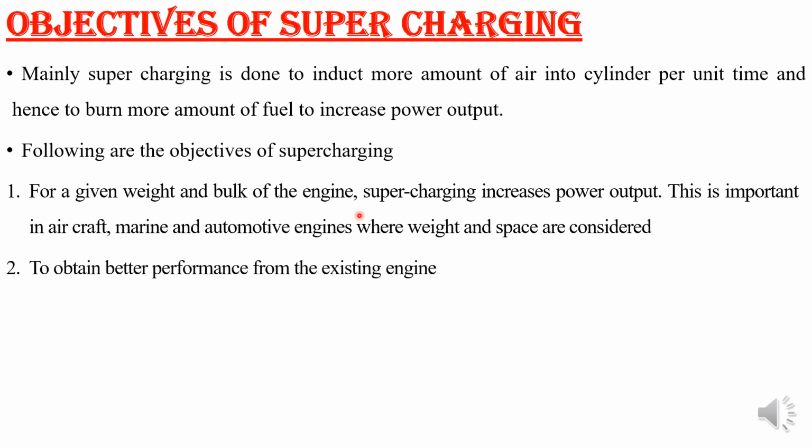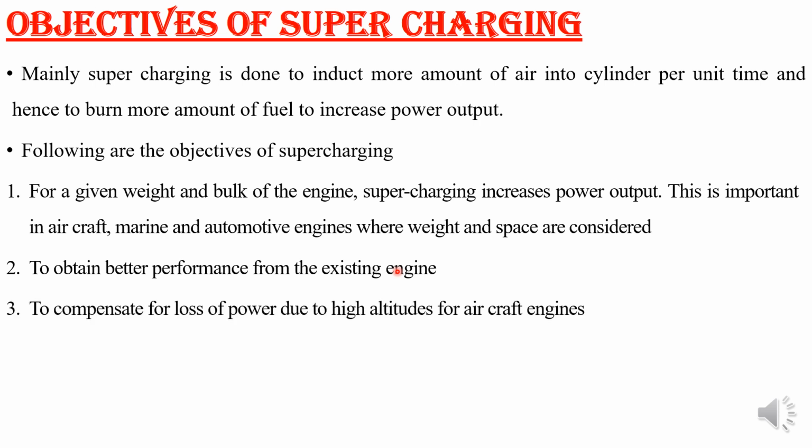Next, to get better performance from the existing engine. This is the second objective of supercharging, and the third one is to compensate for the loss of power due to high altitudes for an aircraft engine. Whatever loss of power there is has to be compensated by this supercharging device. So these are the three objectives of your supercharging engine.